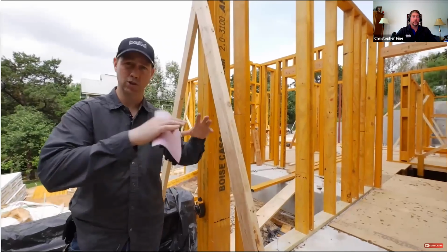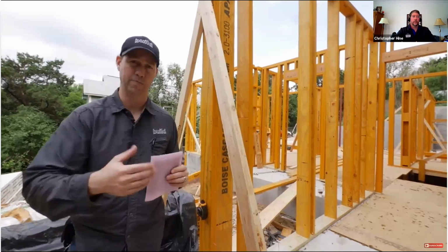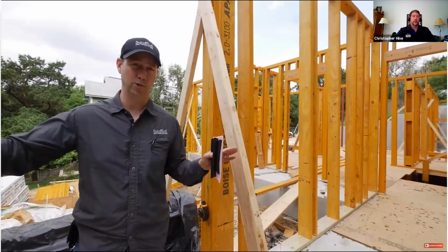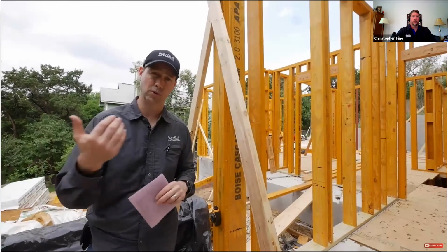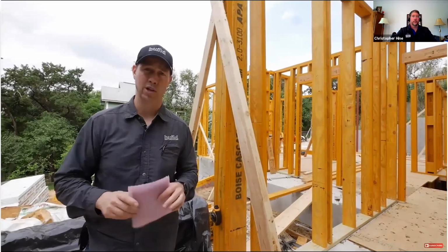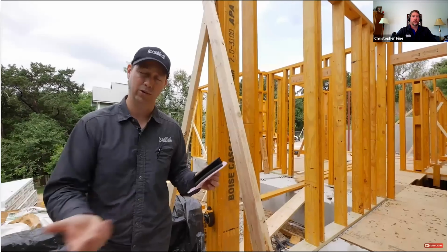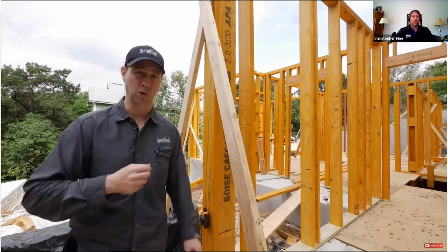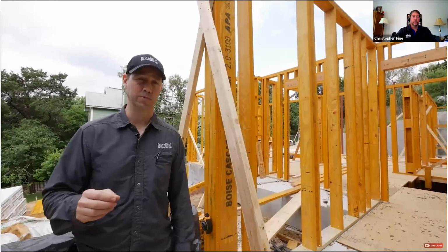Number one, we can't ever control the indoor air if we can't control air leaking in. When air leaked into an older house, it brought with it all kinds of outdoor contaminants like pollen and mold spores. It also potentially dropped water inside our wall cavities. As I've done a lot of remodeling, I find a lot of mold on the back of sheetrock from air leaks that came in. That humid air hit a condensing surface and mold was growing inside those wall cavities. So it's really important for us to air seal.